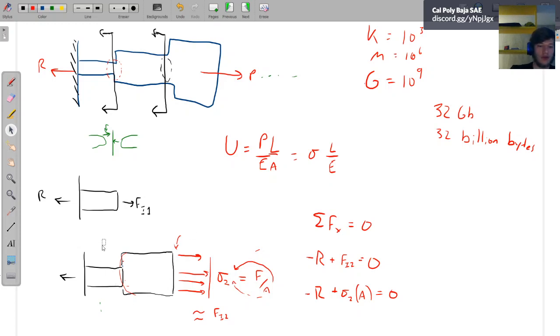So, since we know we can use cuts appropriately like that, now I said last time we calculated what the stress was here. The stress here and here have to be different because the areas are different, and there isn't any other force. So we have the same force P. This same force is being applied throughout the whole body. Everything in here experiences this force, but they all have different areas.